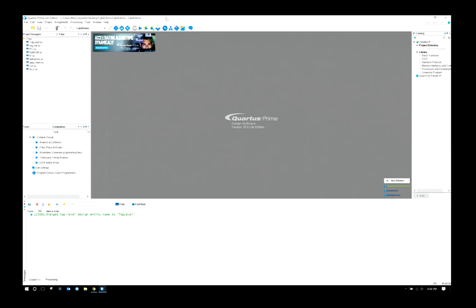Make sure they're clear on the difference between the top level for a single. Yes, yeah. So remember you guys saw top level TB before, and I didn't add that to this project. So what you're going to be doing is when you're running your test for the whole thing, you're going to add all the TB files to ModelSim, and I'll show you guys an example of that. You don't want to add it here because it'll be weird.